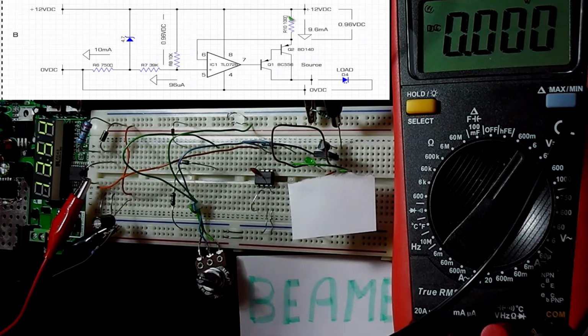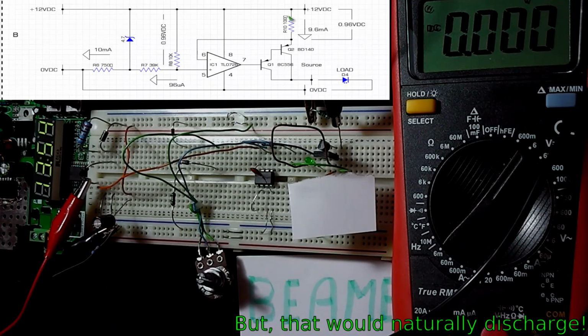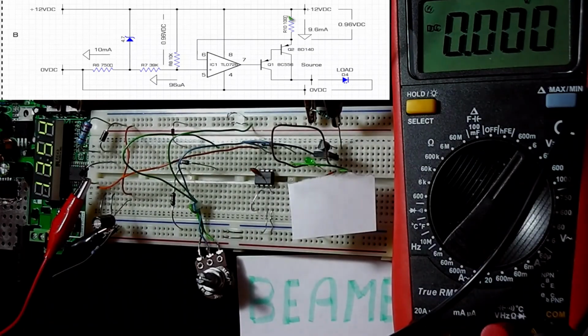You could lift this op-amp via perhaps a cell, 1.5 or maybe a 3 volt cell, and that would be raised above the compliance voltage of 12 volts. And incidentally, I've adjusted the 12 volt supply. In fact, it's running here by the looks of it about 13.5 volts, nearly 14 volts, because I wanted still 12 volts across the compliance voltage.